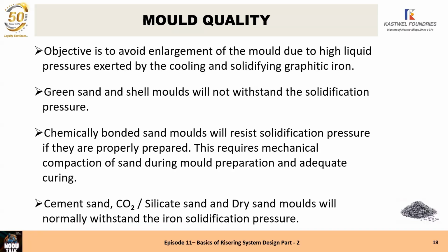Let us see what is known as the mold quality. Our objective is to avoid enlargement of the mold due to high liquid pressure exerted by the cooling and solidifying graphitic iron. Green sand and shell molds will not withstand the solidification pressure.